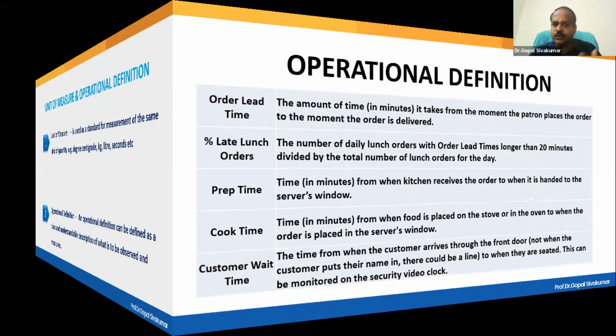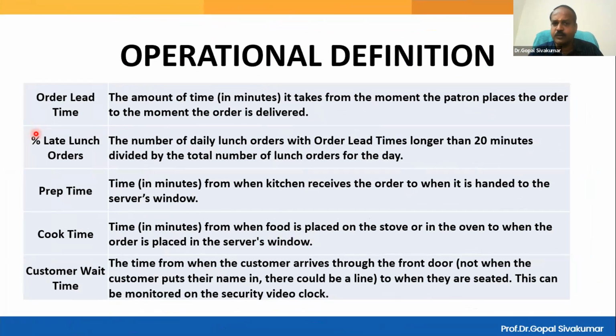For example, how to hold the workpiece, how to hold the measuring equipment, and what should be your posture during data collection, whether you can sit or you should stand. All these things should be clear. And if required, some images, some diagrams, some video clips can be provided. Everything together is called operational definition. The ultimate purpose is we want error-free reading.